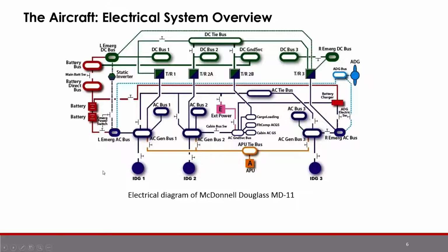It outlines different areas that circuits would be tied to, like these buses and the generators, as well as the batteries. This kind of system you can see is a parallel system, which means that the wires, the circuits aren't in parallel, but these buses are. The buses are giant hubs where other circuits are connected.